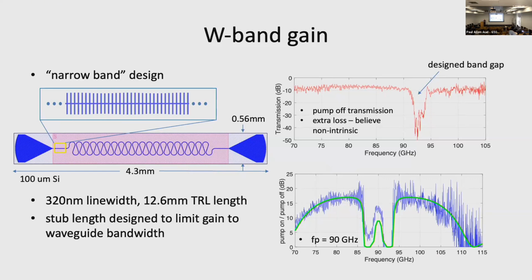Hey, how do you calibrate these measurements? We calibrate them. For gain measurements, we just replace the TWP with a through transmission line. Sometimes at lower frequencies we have switches that work, so we can use a transfer switch arrangement. These are cryogenic switches.